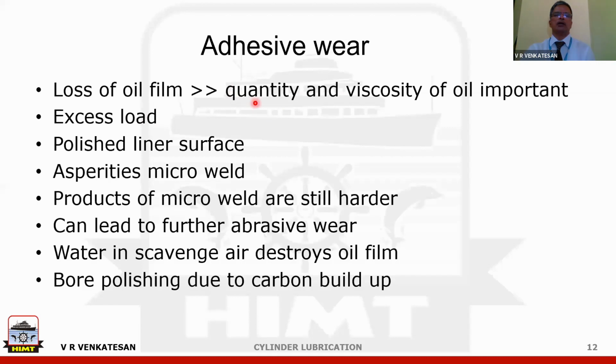For that, the main issues are these. Are you delivering the correct amount of oil, and is the oil in the correct viscosity? Is the entire part of your liner coated with oil? In the place with the highest load, are you able to maintain an oil film? If you are able to do all these things, then the adhesive wear will be less.